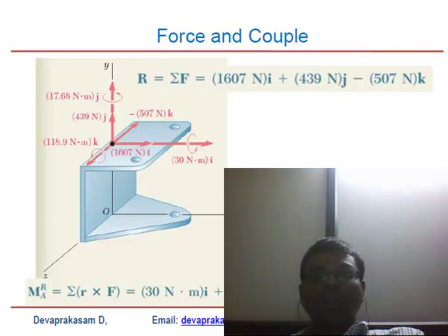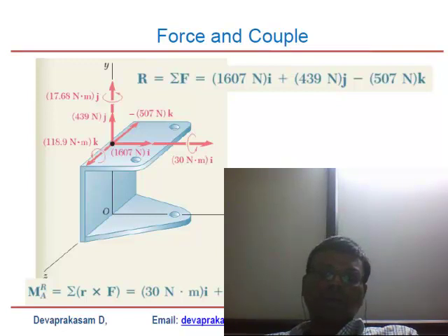This is the way you have to approach any statics problem, whether it is 2-dimensional or 3-dimensional. You must understand that you have to find the components of the forces, add these components to find the resultant forces, and find the unit vectors, projecting them to the magnitude of the force. That would give you a vectorial representation of the force in the x, y, z direction.